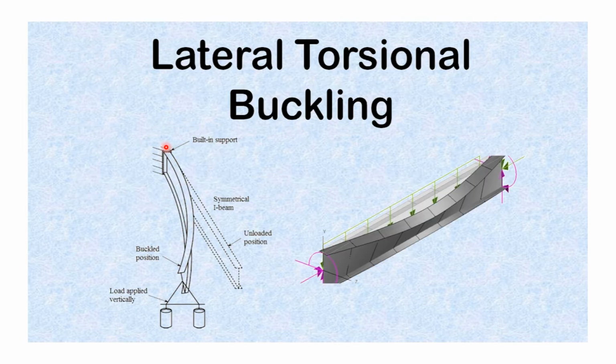Here is a beam fixed at one side, and you can say hinged on the other side. Then due to the twisting of this beam, this is called lateral torsional buckling. The member can twist. Here is a channel section. When the load is applied, the channel has the tendency to twist. Similarly for an I section, if there is side sway loading or an eccentricity, there is a good chance that the beam will buckle and twist at the same time.